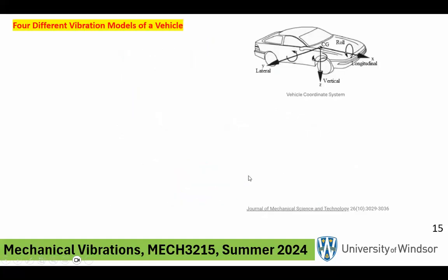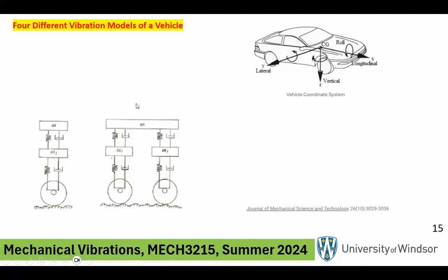If you look at a car, and those of you who have taken a vehicle dynamics class have gone through this, you can replace the car, which is very complicated, with a quarter model representation of the car, where everything in the car, including the mass of the compartment, the mass of the engine, and the springs in the suspension, is still represented by a situation like this. As it is right now, you can think about it as a 2 degree of freedom representation of the vibration of the whole car. Or you can look at it in this fashion.